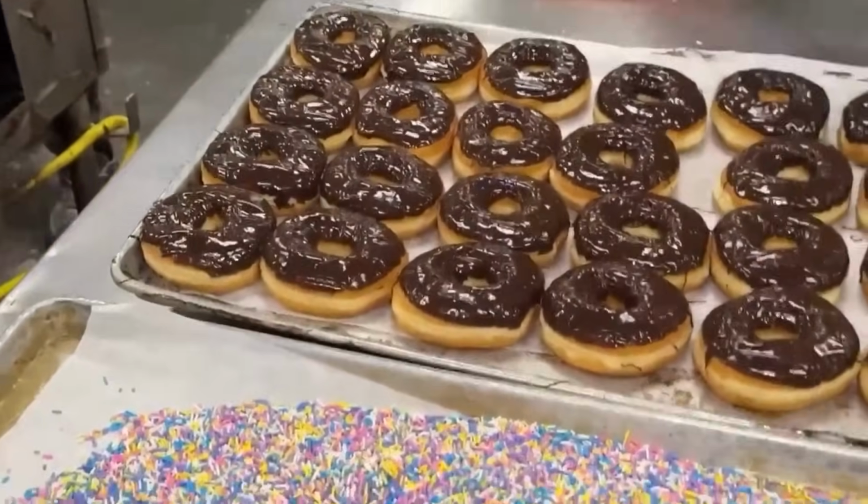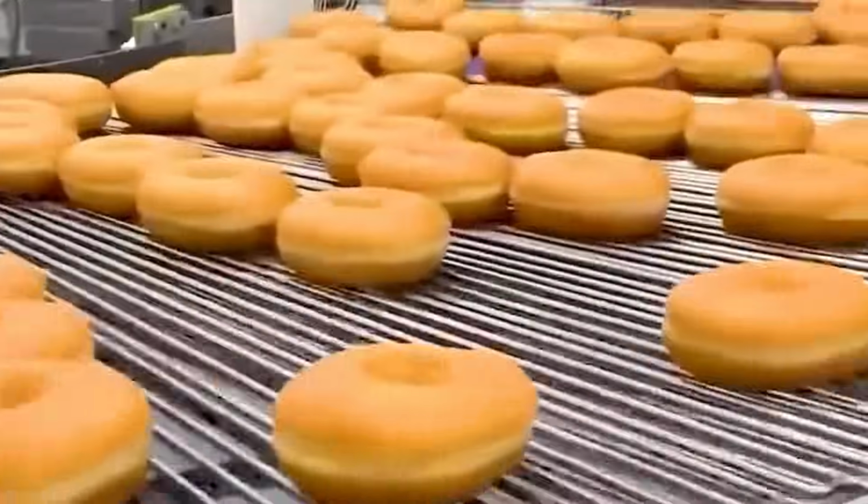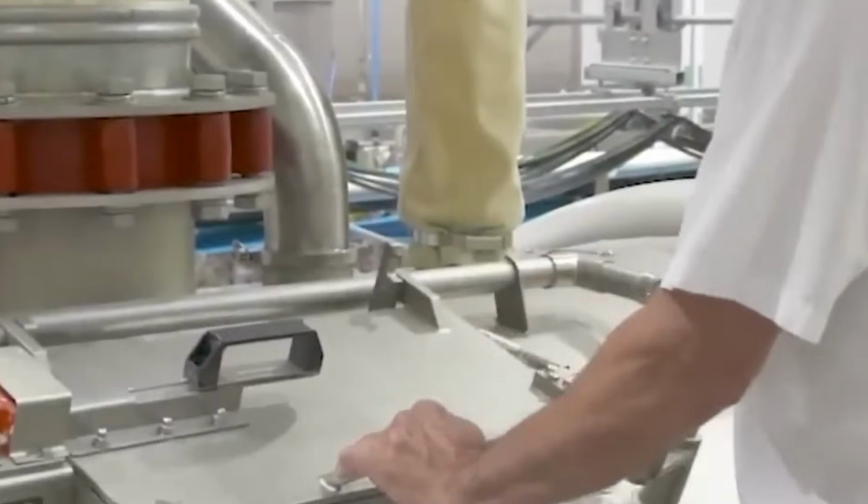Packaging is handled by an automated tray loading system. Flat-folded paperboard trays are erected using mechanical arms, and donuts are placed inside via pick-and-place robots with suction grippers. For assorted packs, robotic arms select donuts by type from buffer conveyors. Trays proceed to a lid applicator station, where pre-folded lids are pressed and sealed using glue jets or heat-sensitive adhesives.